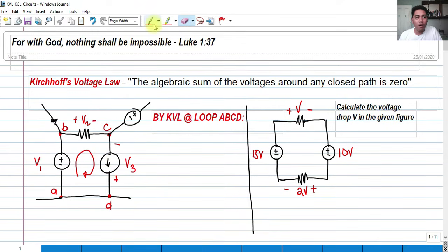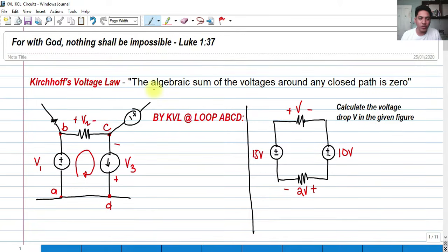So if we are going to write a KVL equation, in KVL you will be the one to write those equations, okay? So for example, we arbitrarily selected our flow of current. Obviously, there will be a flow of current inside this closed loop, in clockwise direction, and we call that clockwise direction the conventional current. Okay, so how do we write KVL equations? So for example, if we are to get the KVL equation around this closed loop